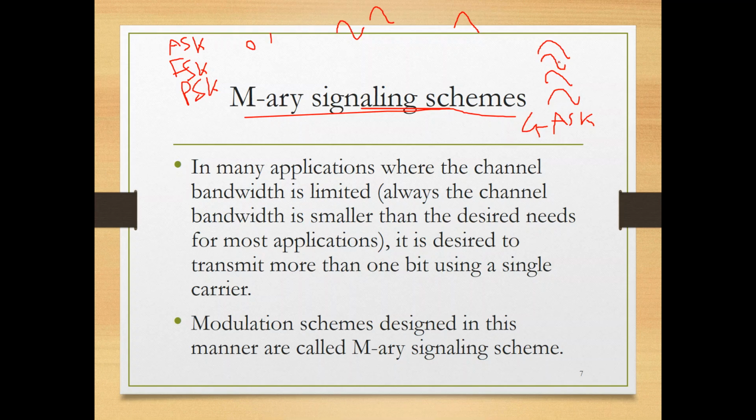I want you to tell me, when the number of levels goes up, what happens to the data bits that I map? They increase. More levels, more data bits for each level. This means that you increase the spectral efficiency, you send more data bits, you increase the speed of the internet, the throughput.